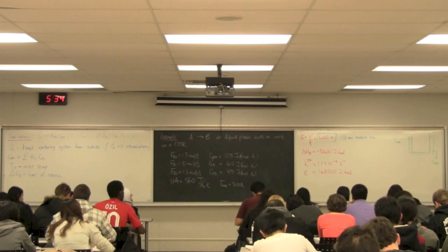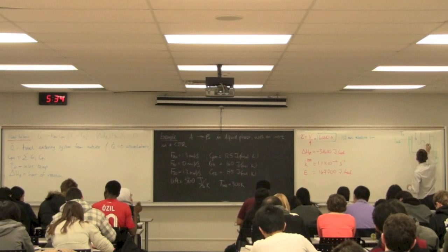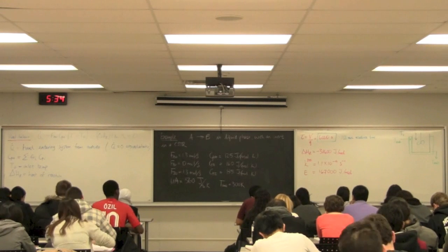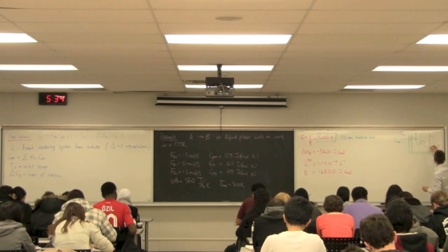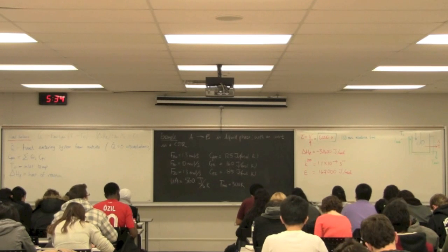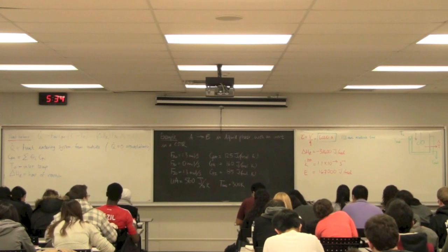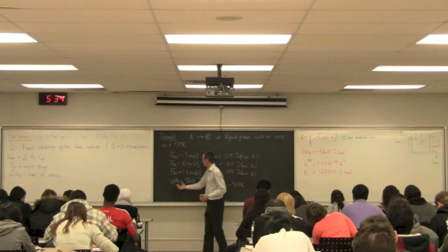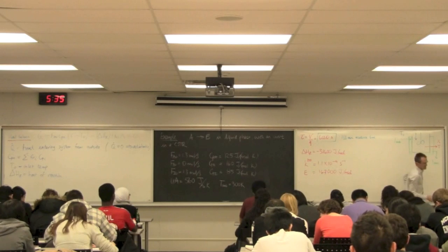There's an inlet temperature T0, but that temperature is only the inlet temperature. The contents of the reactor are well mixed, and leaving the reactor is a certain temperature T. There's also a conversion X and a concentration. All the properties inside the reactor are also the ones leaving the reactor. So this U times A term is the product of the heat transfer coefficient multiplied by the surface area available for contact on the CSTR.